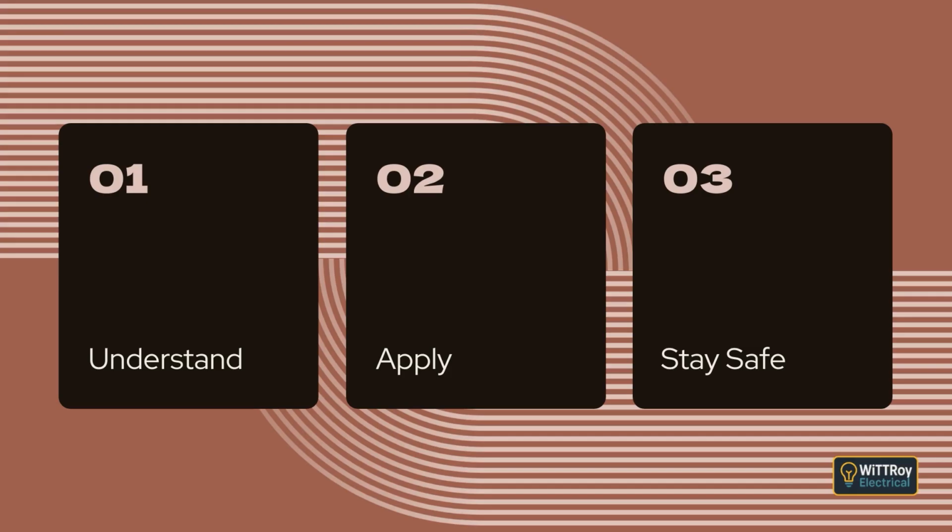It must also be manually operated, clearly marked, and must reliably stay in the off or stop position until reset manually. The device must not re-energize automatically. Power must only return once a person intentionally restores it by operating the switch or control. This prevents machinery from restarting suddenly and injuring someone.